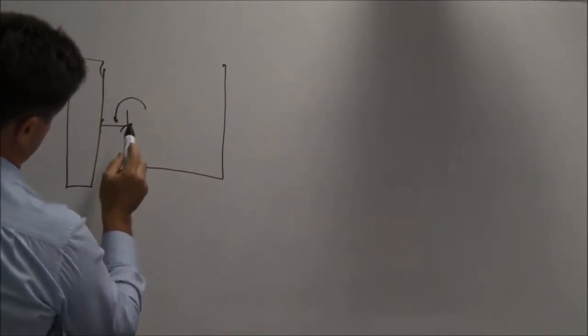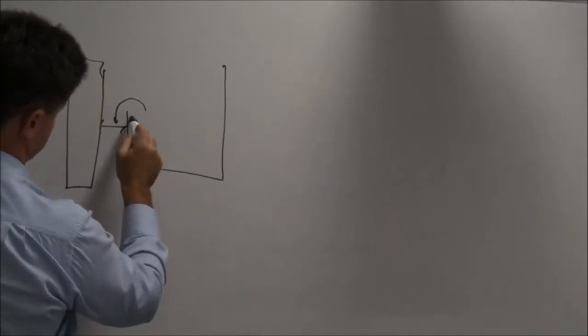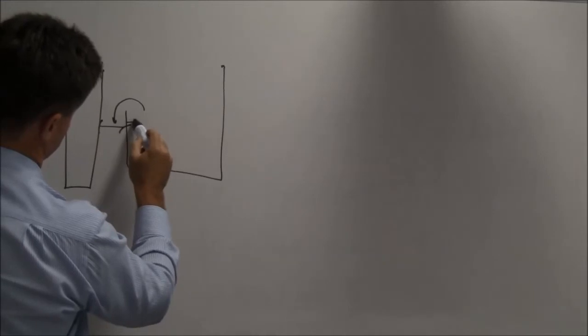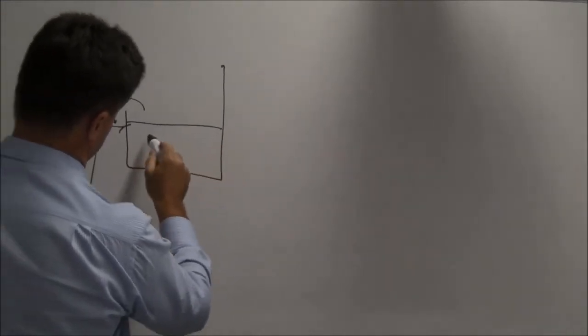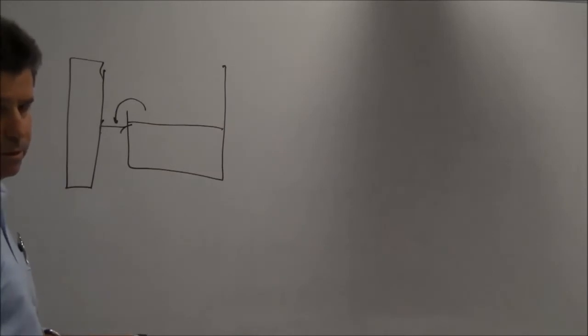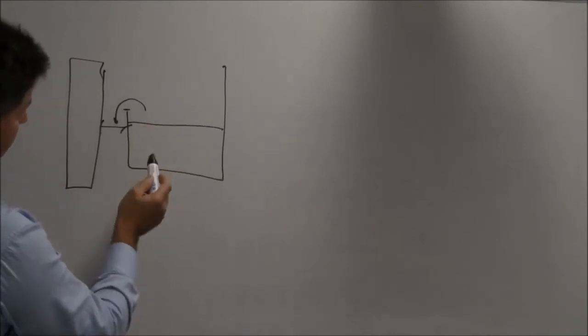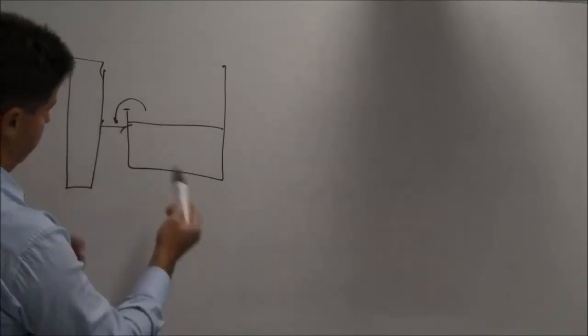But again, we still provide a freeboard, even with an eaves gutter. It's not much, but just to make sure that the water, when it's being designed, is not lapping at the edges. So you might give yourself 10 mil or so below the top, below the back of the gutter, whichever way. Obviously it works in reverse.